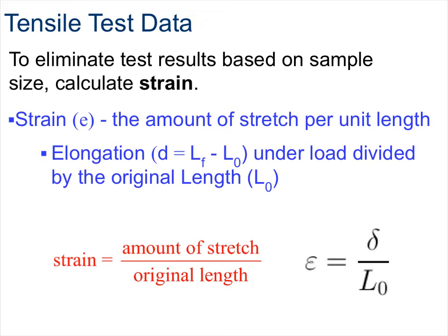Returning to the previous example of the 10-inch long plastic rod, if the total change in length is 1 inch, then the axial strain will equal 0.1 inches over inches, or 10%. This means that 0.1 inches of elongation occurred for every 1 inch of original length, which represents a 10% increase in the length of each unit as well as the overall length of the member.